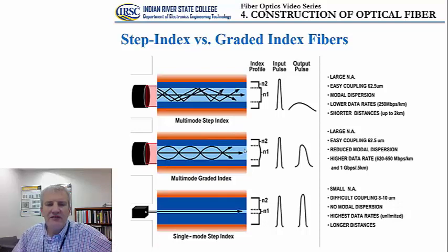and having different layers with different density would cause an additional bending of the light. In other words, different modes will not be propagating along straight lines that are bouncing back and forth, but would rather be curved. That's going to affect the total length that certain modes are propagating in the glass core. They will be arriving at the other side of the optical fiber much sooner than in the case of the modes in the stepped index fiber.